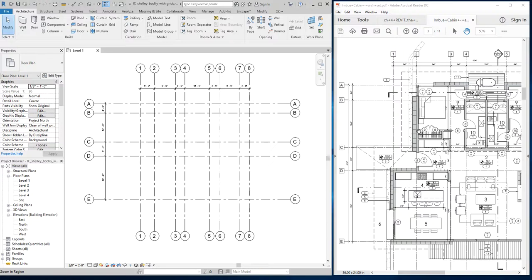So I want to say that. I also want to say that this is kind of a technical type operation. Not in that I can't teach you how to do it, but when you're creating wall assemblies, you sort of need to have some knowledge as to what a wall assembly looks like, right? So this is where beginning designers who have no experience in the field know how to create the walls. They get that, right? But you're like, well, I don't know, maybe how big a block of CMU is. I don't know the width or depth or height of a block wall, right? I don't know all the different sizes of metal studs. I don't know where the vapor barrier goes on a wall. I don't know what the air gap behind masonry is. And these are things you build into the wall assembly.